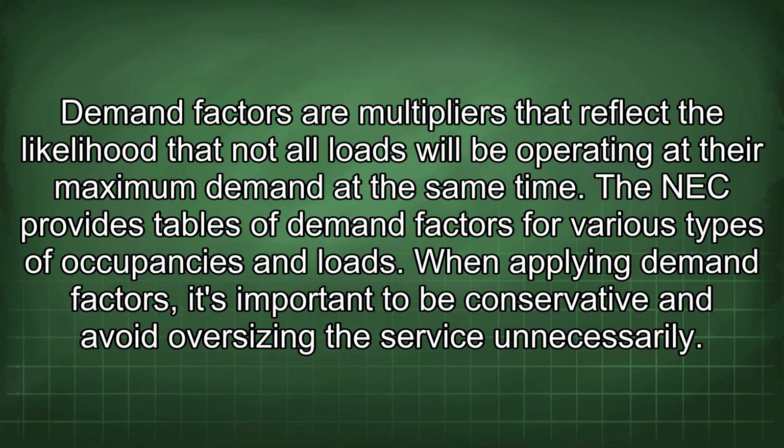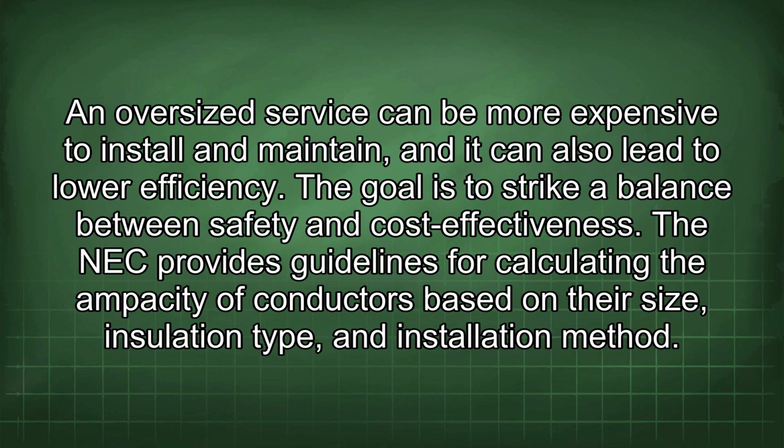When applying demand factors, it's important to be conservative and avoid oversizing the service unnecessarily. An oversized service can be more expensive to install and maintain, and it can also lead to lower efficiency. The goal is to strike a balance between safety and cost effectiveness.